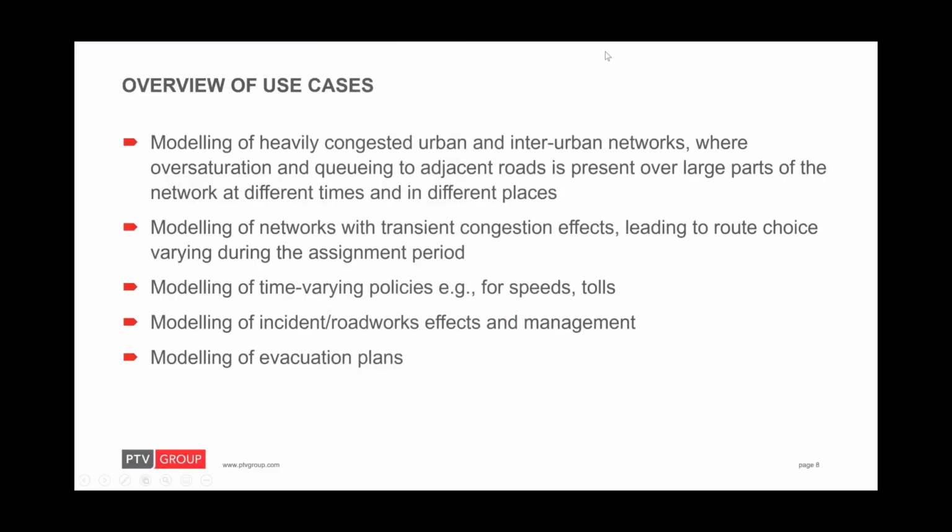All right, overview of use cases. Typically, simulation-based assignments would be used for modeling of heavily congested urban or interurban networks where oversaturation and queuing to adjacent roads is present over large parts of the network at different times. So if you have a lot of congestion where there's queue spillback and so forth, particularly in some corridors, you may want to use mesoscopic or dynamic assignment, which models the queue spillbacks in those specific corridors or focus areas.